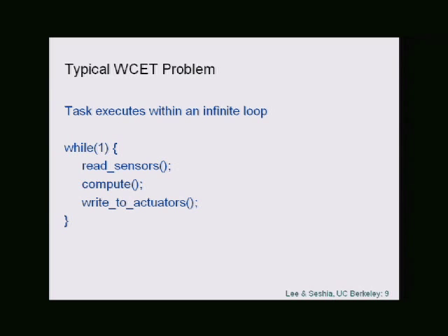So he has 10 rules to follow when you're coding embedded systems software. And one of those rules is to make sure all your loops have statically known bounds. You know the bound before you compile, right? I think this has got a lot of traction within NASA, for example, in implementing their systems.